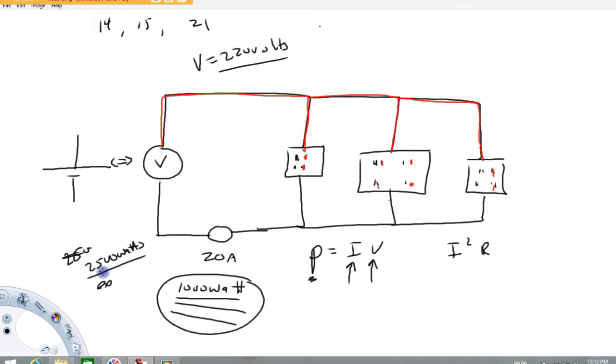If this number is less than the wattage given, you can't plug any of them in. In my example, they gave 2,200 watts. Again, I'm looking at part B. If, for example, this calculated power came out to be 5,000 watts, I could plug one of these in, I'd draw 2,200, which would be fine. If I plugged two of them in, I'd be at 4,400 watts, still fine. But if I plugged three of them in, I'd be at 6,600 watts, which is over the 5,000, no longer fine. So that's how we work part B.